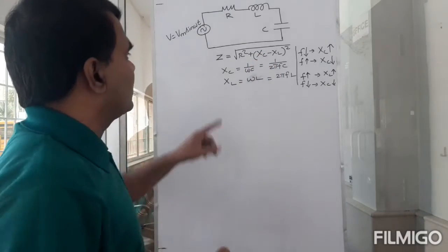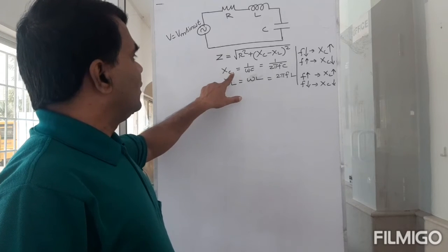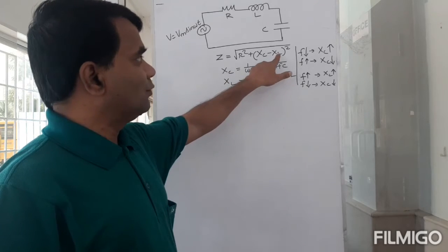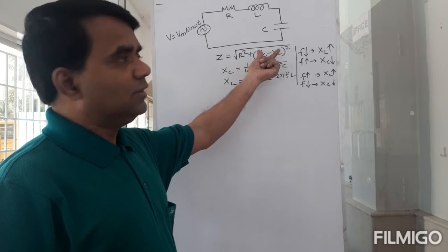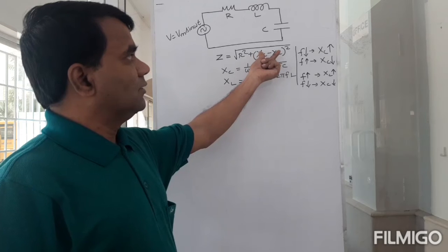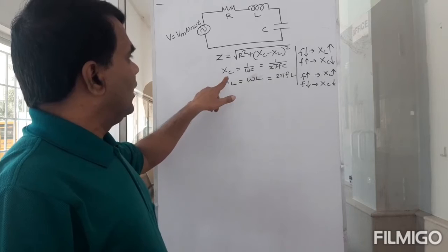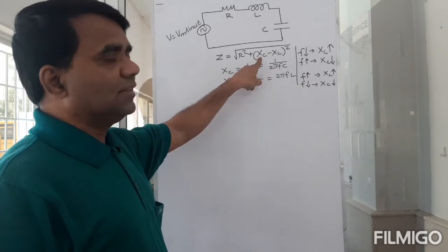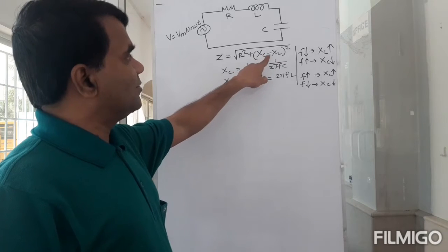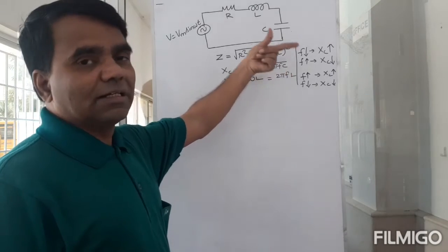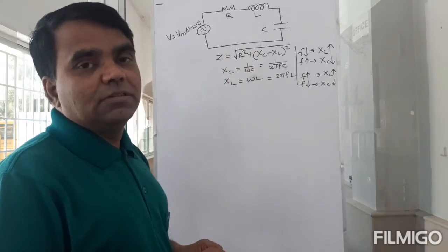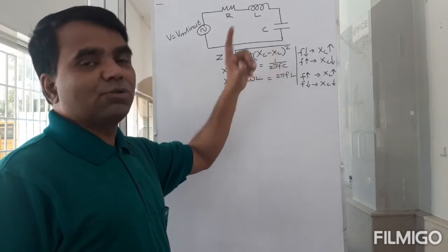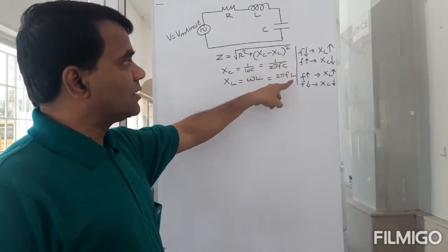And look at this. For some frequency, XC will be greater and XL will be lower. So I can have some values. So this is a positive value, no? It's positive squared. And for some other frequency, a higher frequency, XL can be greater and XC can be smaller. So XC minus XL can be a negative value, but when you square it, you will get a positive value. So notice that you can have the same (XC minus XL) squared value for lower frequency and also high frequencies.